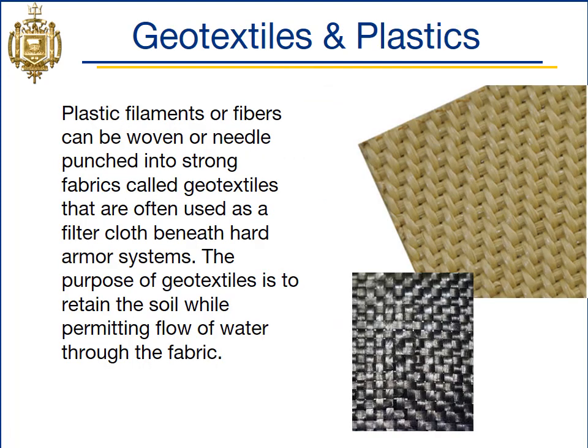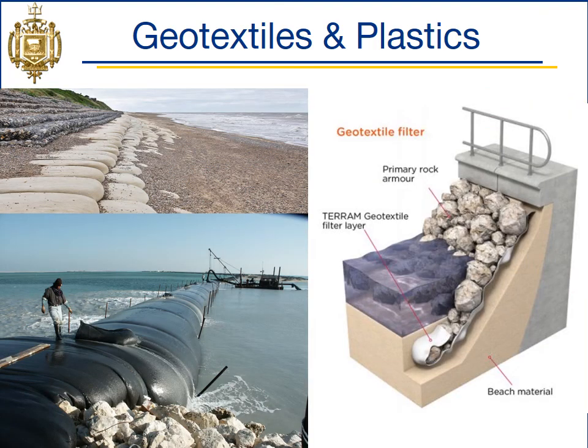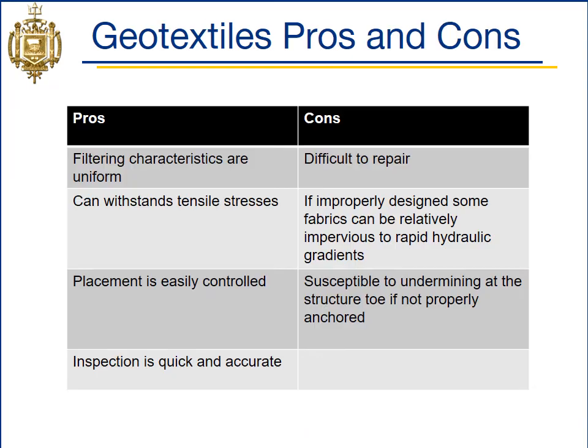Here's a couple pictures of geotextiles. These are used to withhold sand and prevent it from eroding near the coast. Here's a picture of a couple of geotextile bags, also known as sandbags, and they do an excellent job of preventing erosion near the coast and providing structure to prevent inundation of water on the coast. A pro of geotextile is that it's easy to place, but a definite downside is that it's difficult to repair. Once the fabric breaks, it's hard to repair without fully replacing the bag.